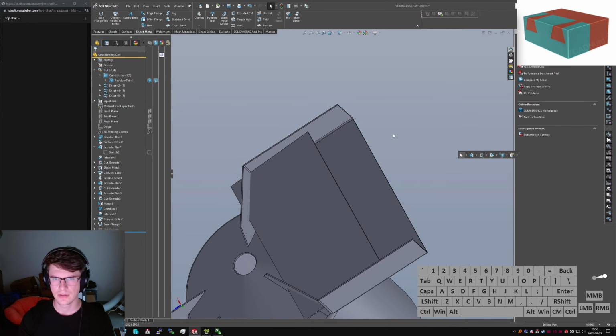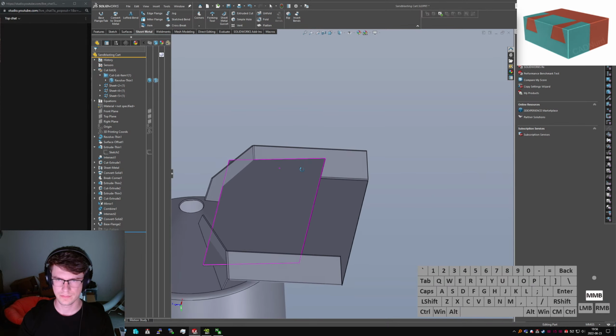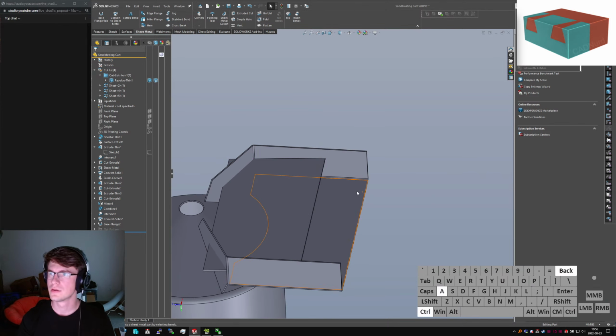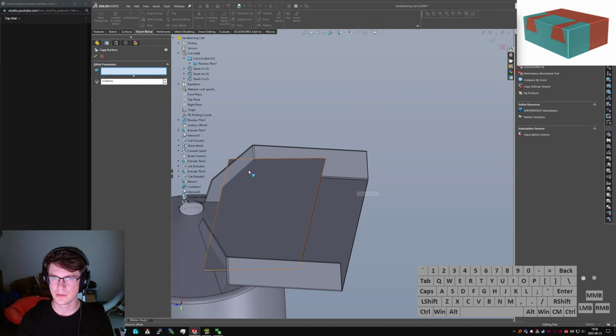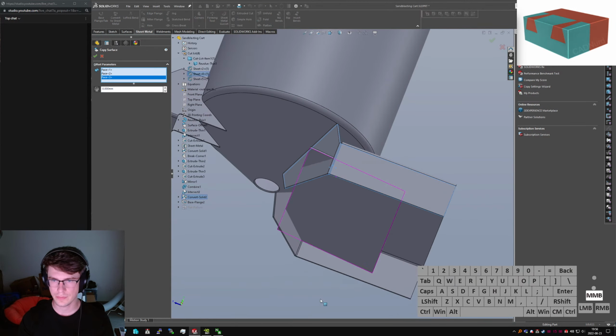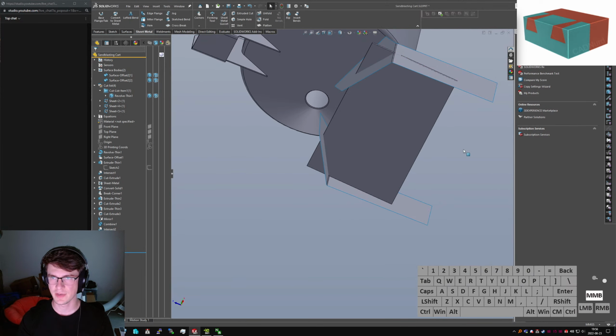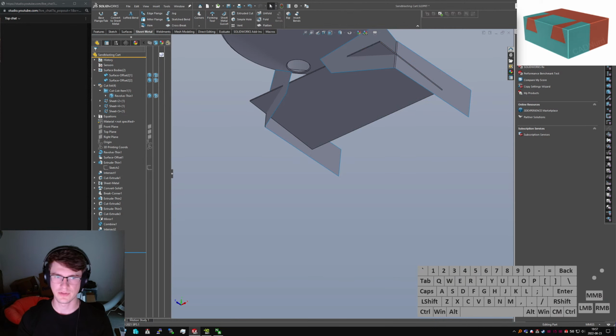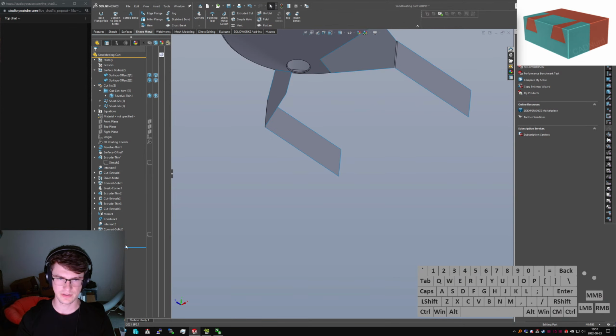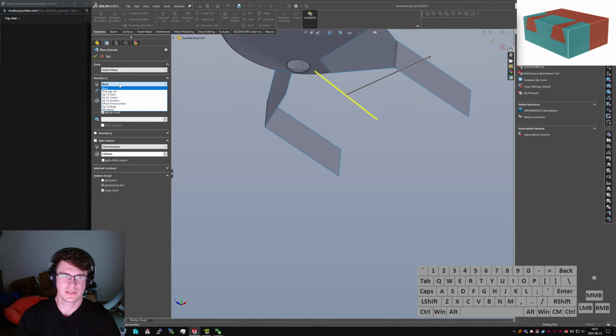Could be wrong. Let's do four offset. Boop, boop. Boop. Create two new surfaces. Hide the main body. Intersect. Ah, I can't. It's quite rude. So in that case, I'll do this instead of as a base flange, an extruded boss, because this doesn't really need to be sheet metal yet.